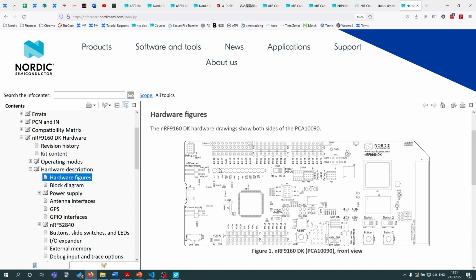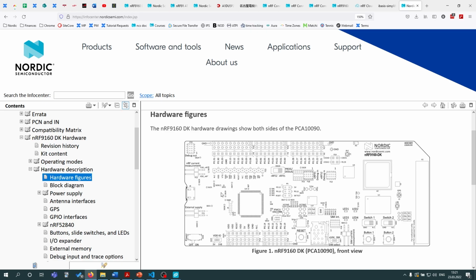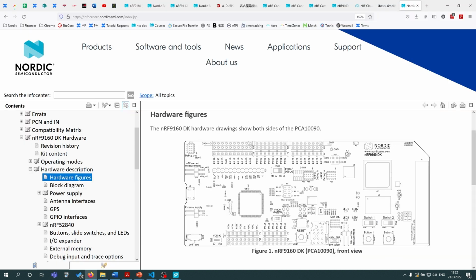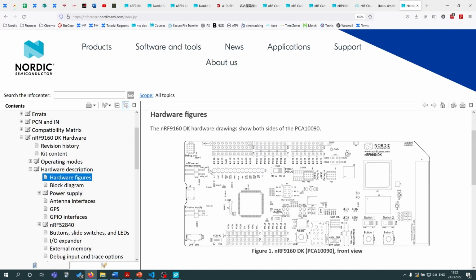Now next, so pin 2, the SDA, I will actually connect to pin 30. So that is this one here, pin 30. The SCL, so that is pin 3, I've connected to pin 31 here. And last but not least, we have the ground pin, so pin 5.